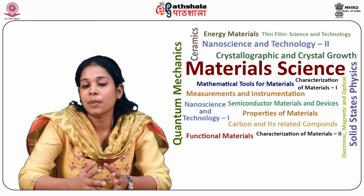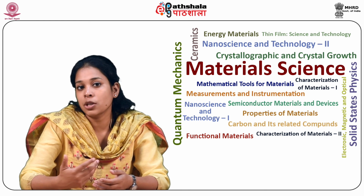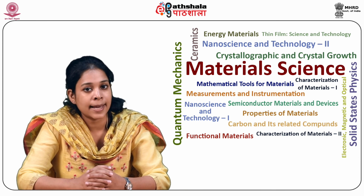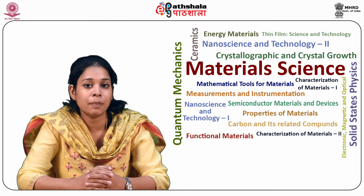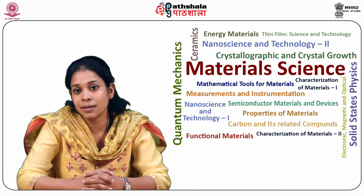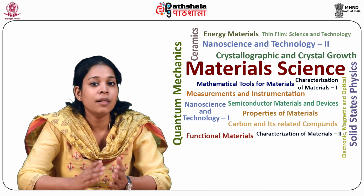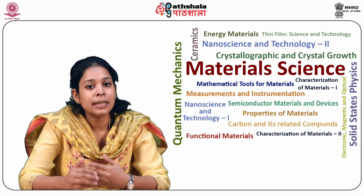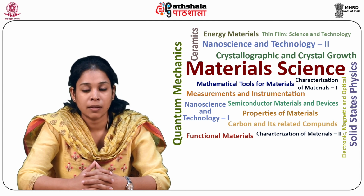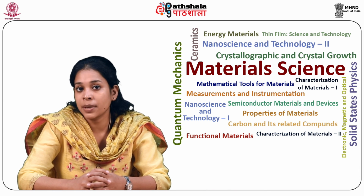A thermochemical process is utilized where the heat treatment of the transition aluminas obtained from bauxite is done at temperatures of about 1100 to 1250 degrees Celsius, and then milling is performed to obtain the alpha alumina powder needed for the preparation of structural ceramics. So the applications depend upon the structural materials.